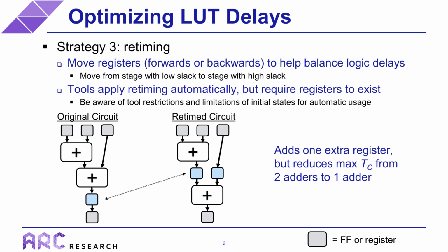Or alternatively, we could have performed forward retiming and moved the 2 input registers on the top adder into a single register on that adder's output, which isn't shown in the figure. So in that case, we could actually improve cell delays and reduce register requirements by 1. Of course, we can't see what precedes the top registers in this example, so we don't actually know if that would be a good idea or not until we actually saw what came before this simple circuit.